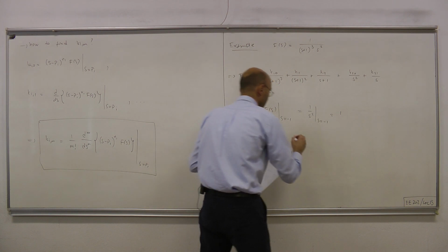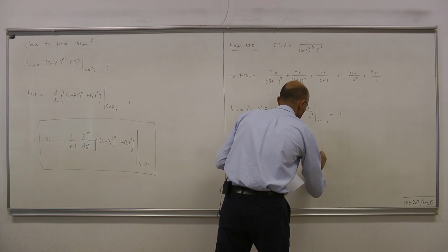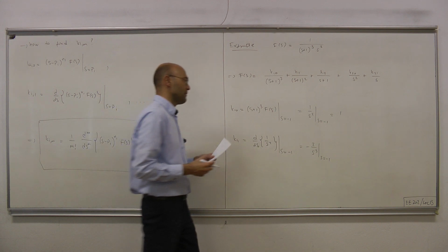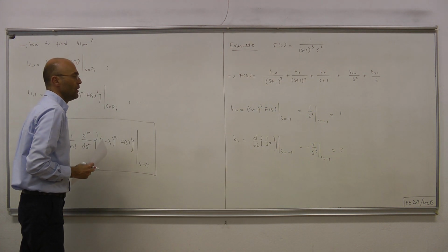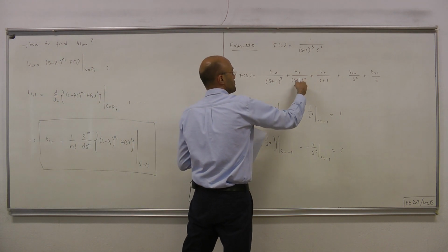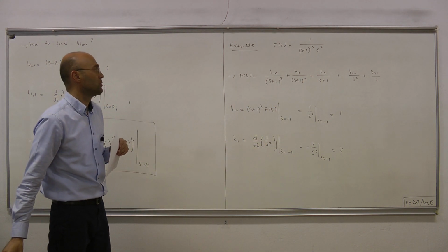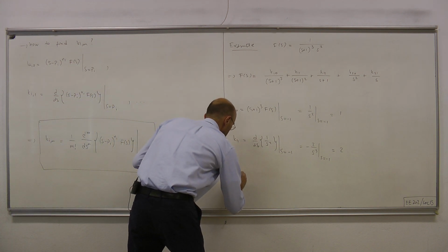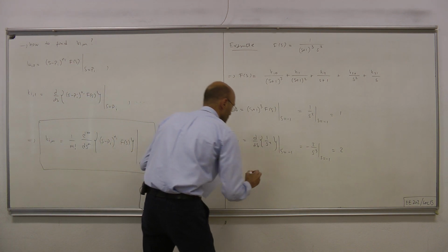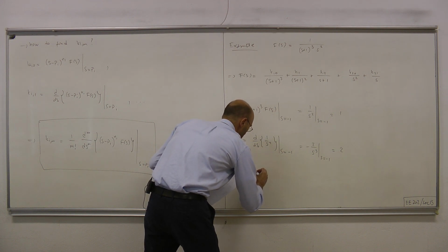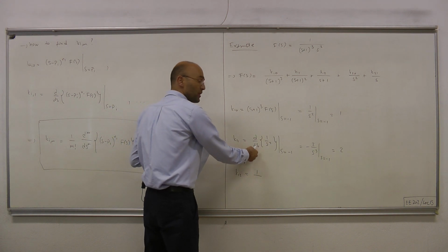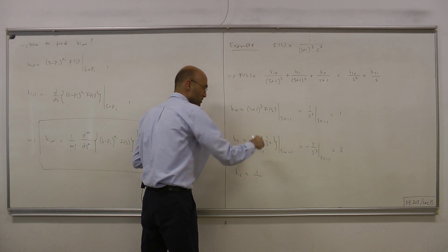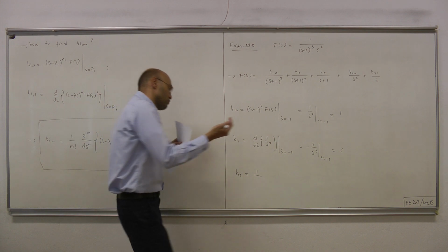So we have minus what? 2 over s cubed evaluated at s equals -1, and that produces 2. And finally, for the last residue corresponding to the pole at -1, which we label as k12, what we do is we have to be careful about normalization. Since we're going to double differentiate, we have to divide this thing with 2 factorial, or simply 2.